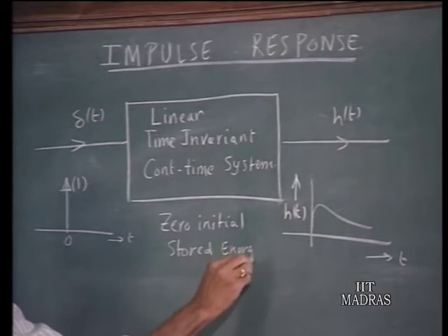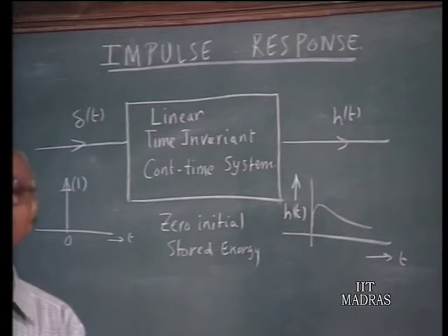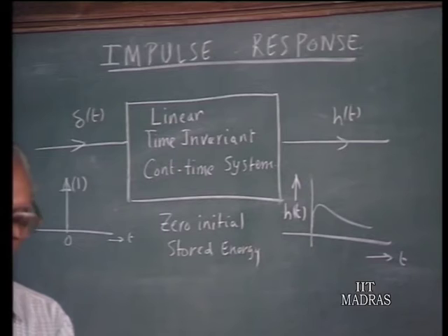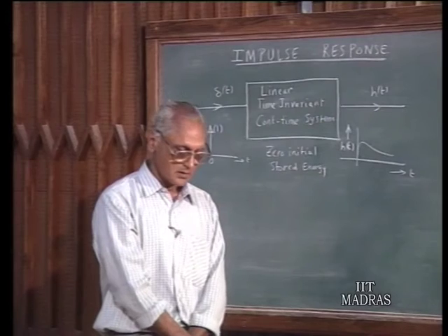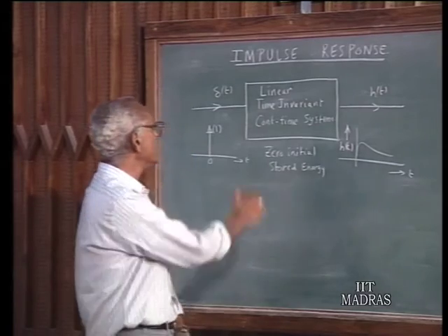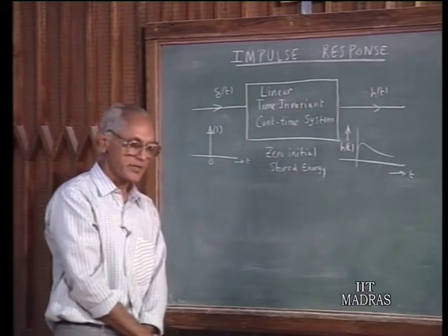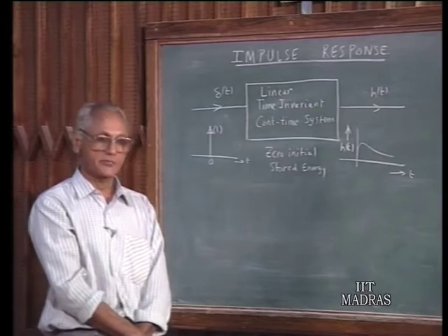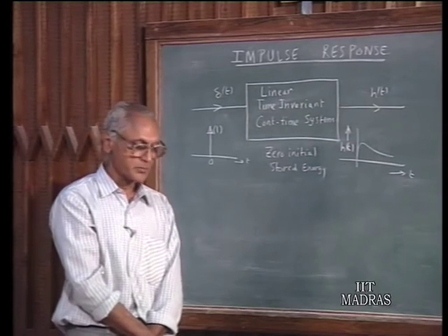The reason is we are going to apply the principle of superposition, and whenever a number of excitations are present simultaneously, the responses could be superposed only if the system does not have any initial stored energy, otherwise the superposition principle is violated.